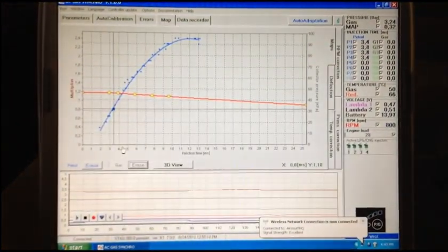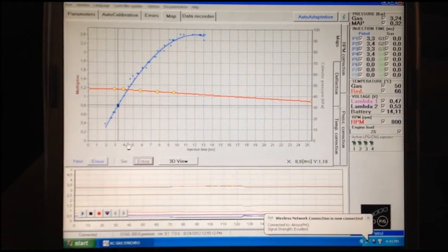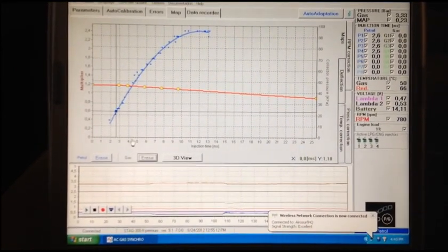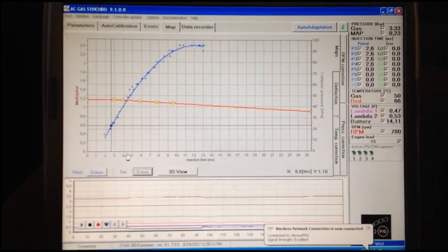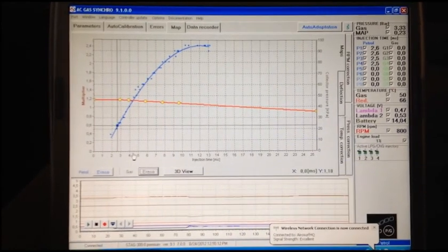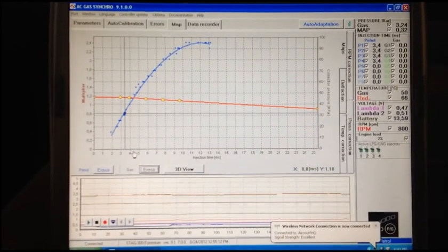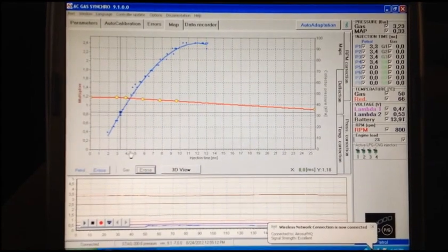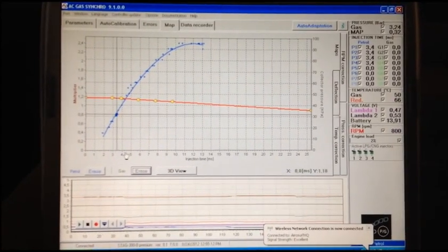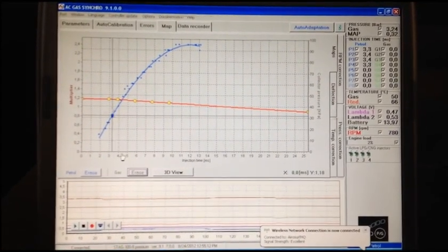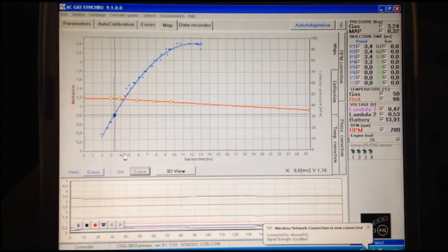But if you really want to get it spot on, you can directly look at this number, or there's an option for an OBD interface that goes along with this kit that'll allow you to pull up right on screen, and it'll show you all your fuel trims. It'll show you all your error codes, things of that nature, and you can also leave that interface plugged into your OBD port, and it will make corrections on the fly.